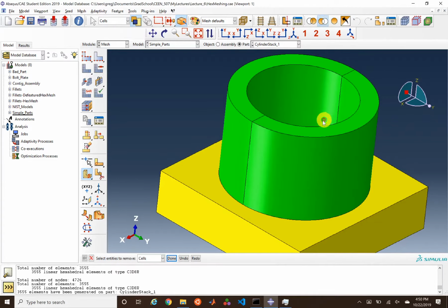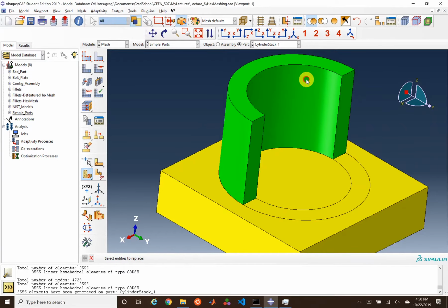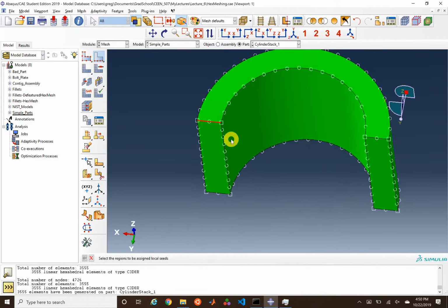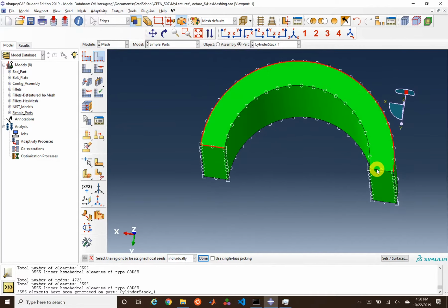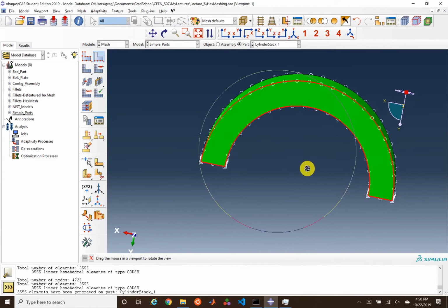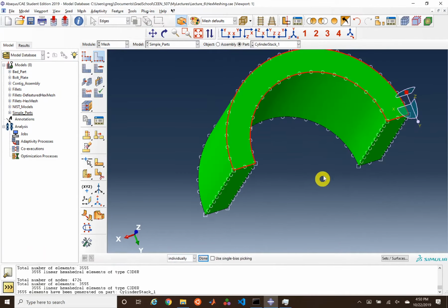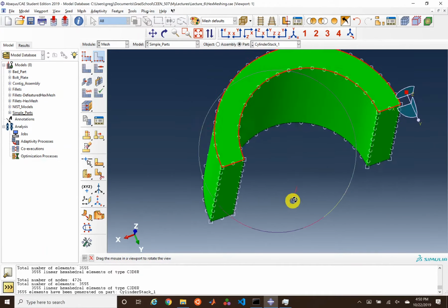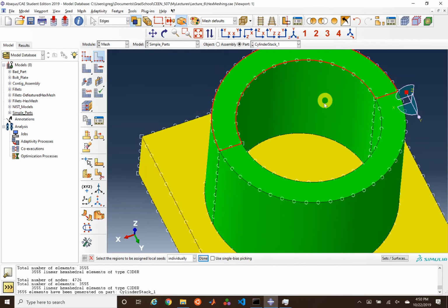And you can see how now, if we look at this cell by itself, we have here's one face of a quad. Let me see if I can select it by itself. So here's one face of a quad, another face of a quad, a third face of a quad, and a fourth face of a quad. So there's your quad. You've shown Abaqus how to put a quad on this surface, and thus a hexahedral throughout this geometry. This has the same topology as a hexahedral element, and so now we can have a structured mesh there.